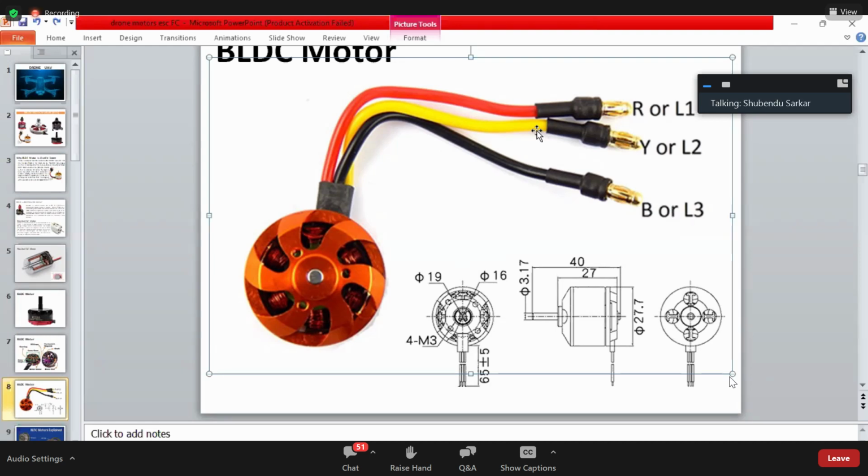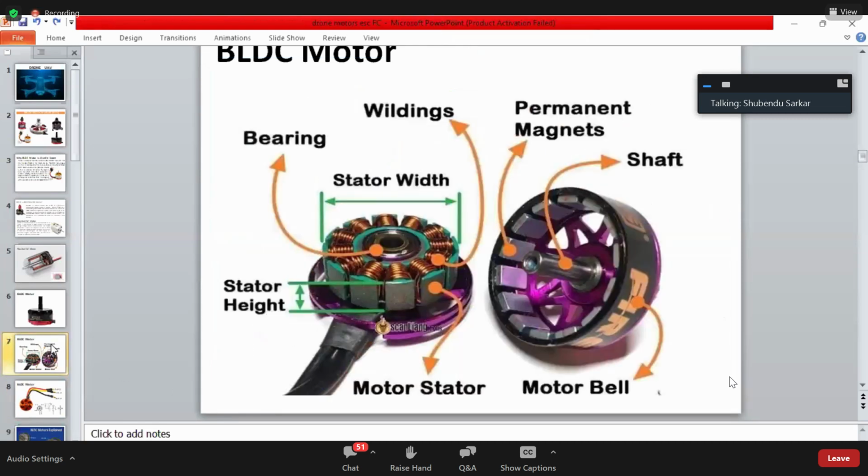In a normal DC motor, we have the commutator, which helps to change the magnetic field's position, so that the push and pull happens over there, meaning it starts rotating. But in this motor, there is no commutator or anything like this. So we need to change the magnetic field on our own, or with the help of a circuit. That is the point. Technically, we want help from somewhere that is going to change the magnetic field for us. And to change the magnetic field, we are going to make the winding in such a way. I'm going to tell you the way.